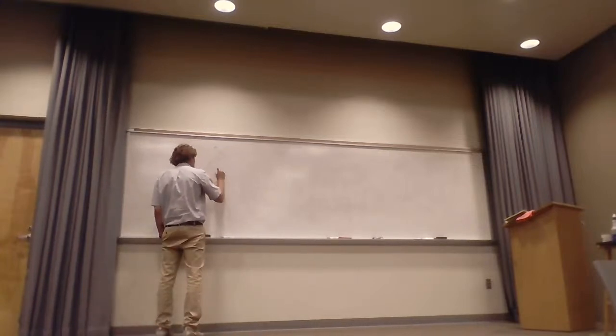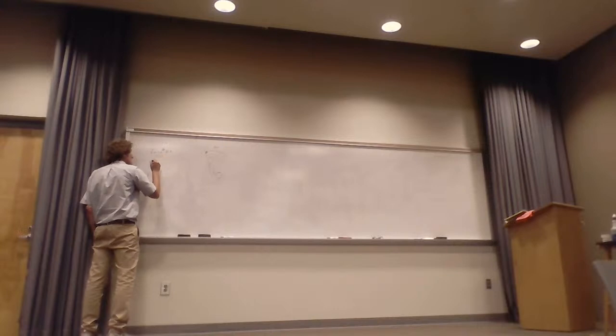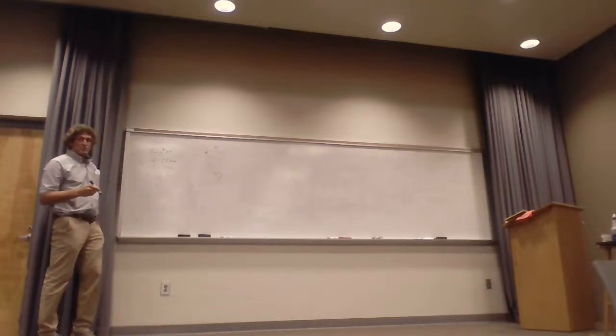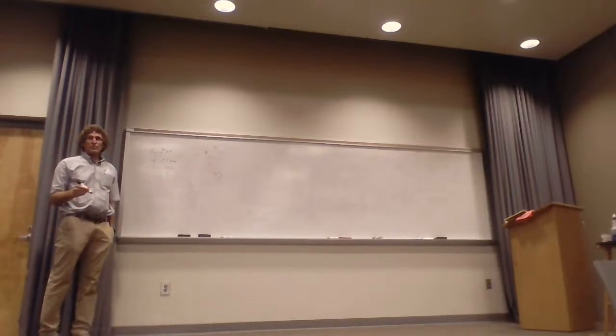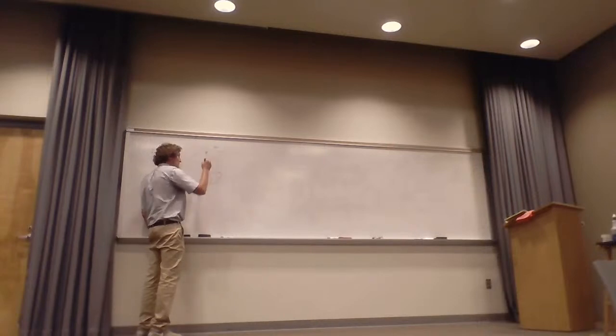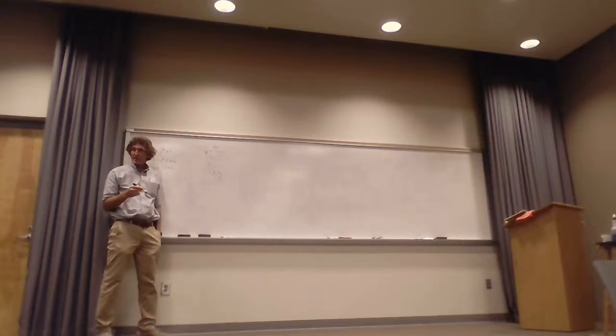You also said there's a frequency of 10 to the 8 hertz. And we also gave the different diameters: A equals 0.5 millimeter, B is 1 millimeter, and C is 3 millimeters. This problem is kind of straightforward. The only thing you really need is the conductivities of the gold and of the aluminum. And the only two radii you need are the inner radius and the inner radius of the outer conductor. Everybody follow me on that?